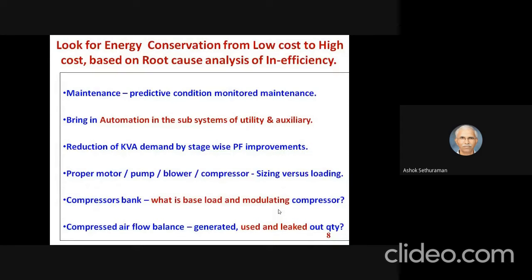That is why the maintenance in the industry is almost, they are having both predictive, condition and preventive maintenance. Most of the industries are doing only preventive condition monitoring. Whereas as an energy auditor, you have to educate the industry for predictive monitoring also with the infrared thermal imager. And if you are having a pump audit, the ultrasonic flow meter also is required.